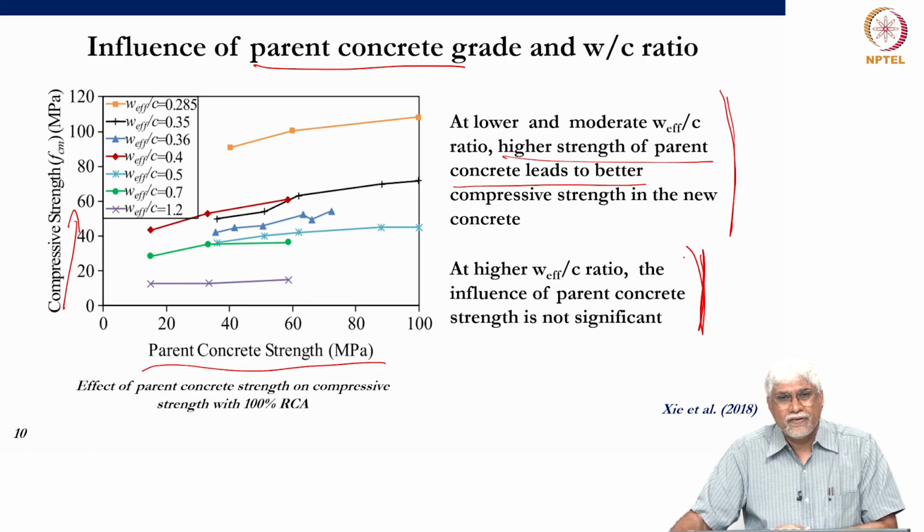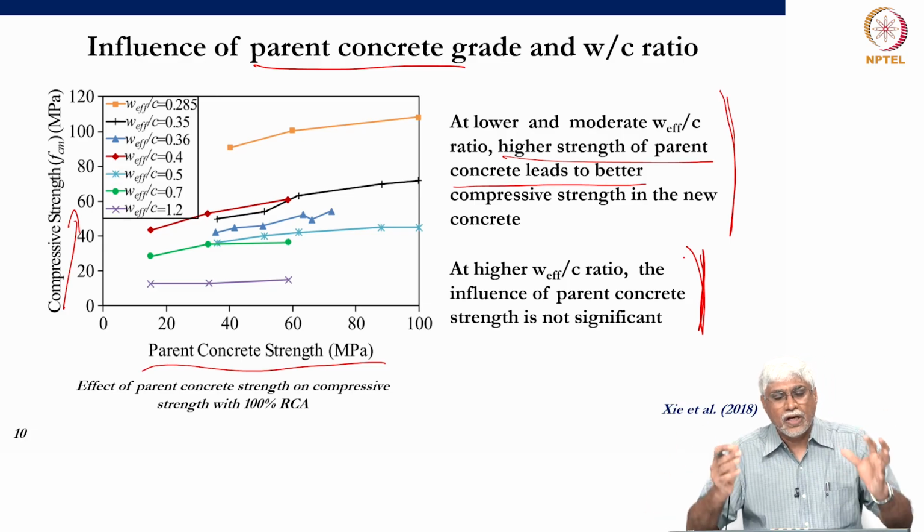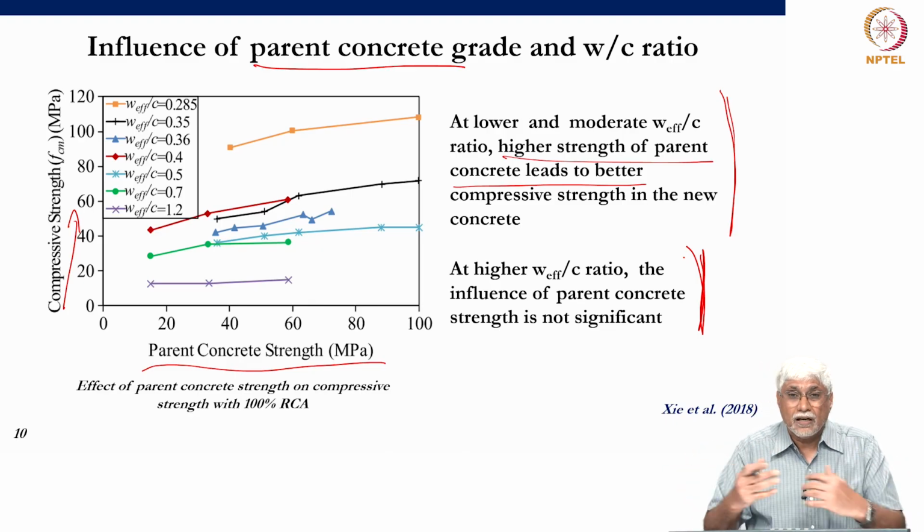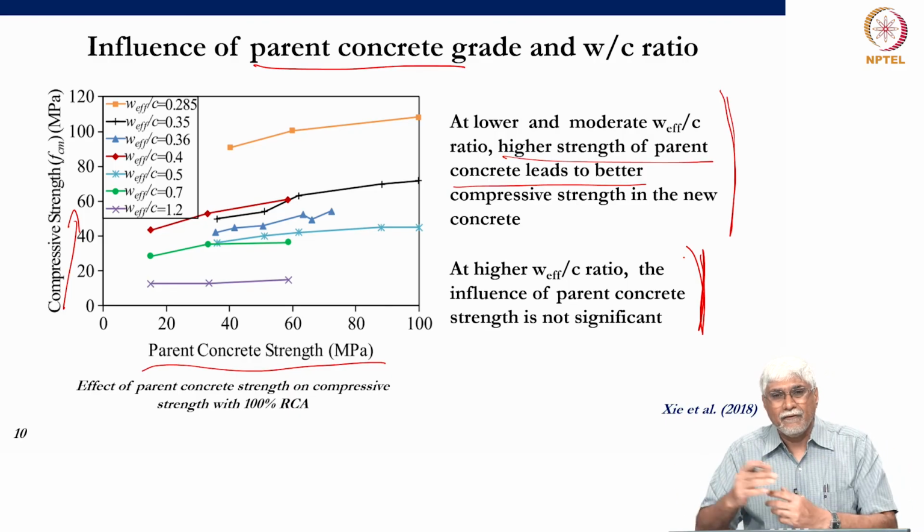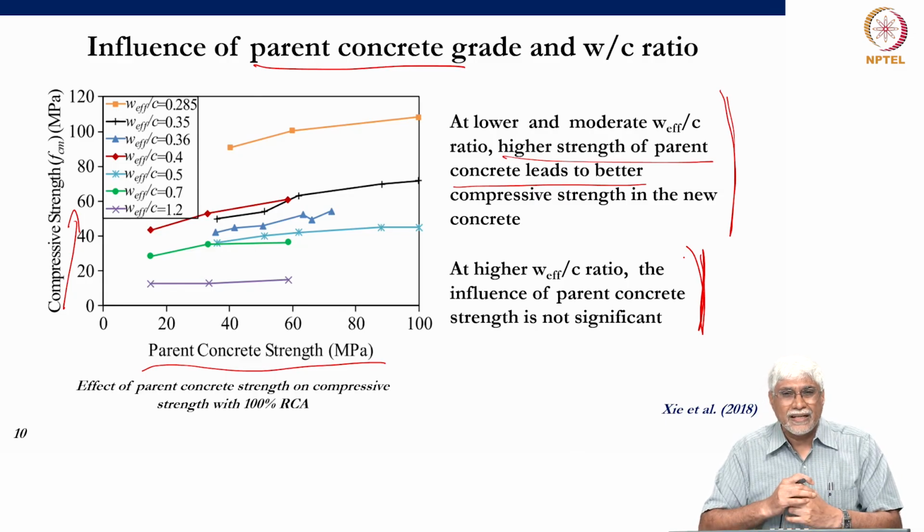The use of recycled concrete aggregates works fantastically where you have a large structure being demolished, where we know the parent concrete strength grade. We can determine the strength of the parent concrete and we crush and use all of that in making new concrete for the same project or for some other project. More knowledge of the parent concrete strength and characteristics will help us use recycled concrete aggregates in a better way.